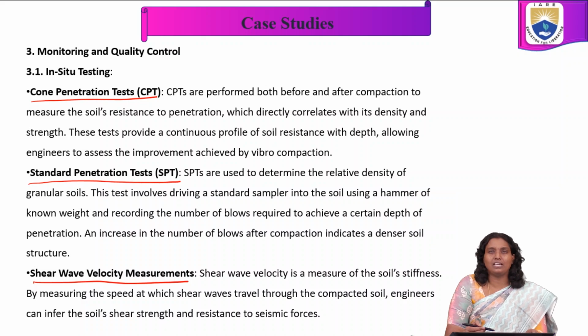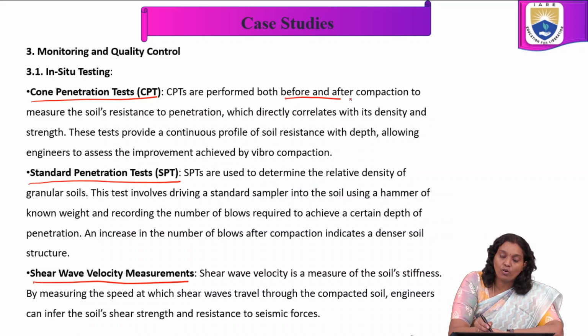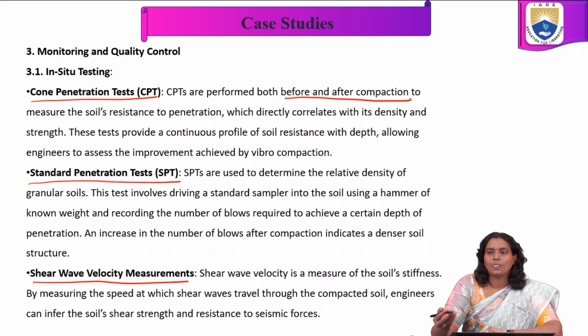In the cone penetration test, CPTs are performed both before and after compaction. Before, what kind of resistance to penetration, what is the density, and after that what is the density; do we get the desired density or not?